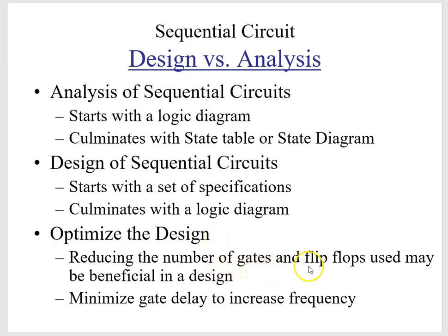And typically flip-flops, we need flip-flops for the states, for the memory elements, and they use a lot of transistors. So minimizing the number of flip-flops can often minimize the number of gates. We also want to minimize gate delay to increase frequency. So these are types of optimizations that we want to do.